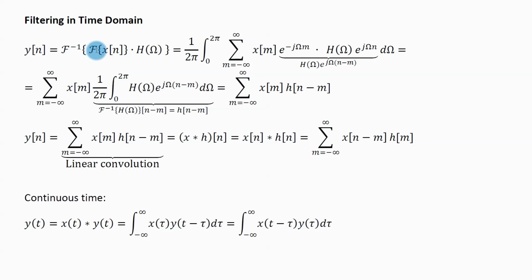So first, this Fourier transform. I need to take my signal. This is my signal, except I have changed the time index from n to m. I will explain why I have changed it later. Now to complete that Fourier transform, I need to take my signal and multiply it by this complex exponential, and then take the sum from -infinity to +infinity. And this entire expression is the Fourier transform, the discrete-time Fourier transform of this signal.